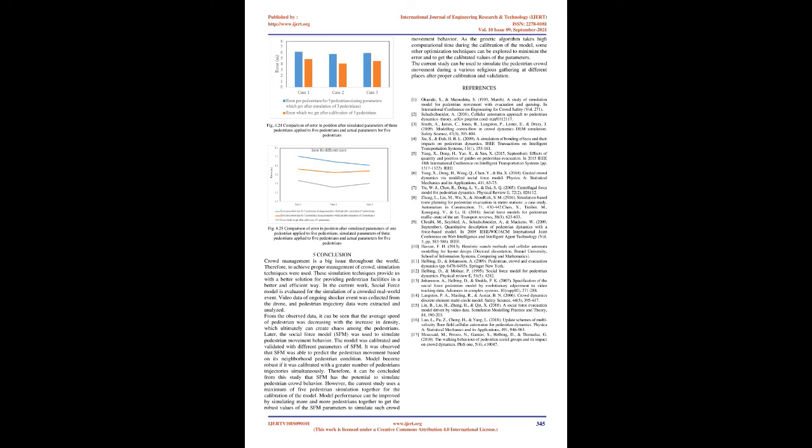Simulation results. As discussed in the research methodology, pedestrians were simulated using the social force model. At the initial level, only one pedestrian is simulated with the help of the social force model, and the parameters were calibrated with the help of a genetic algorithm with their lower and upper bound limits.